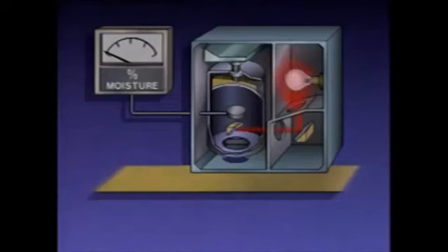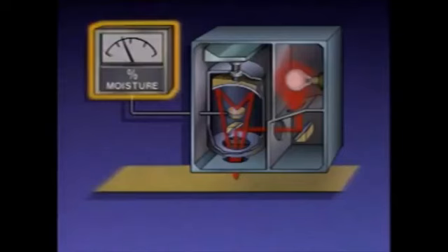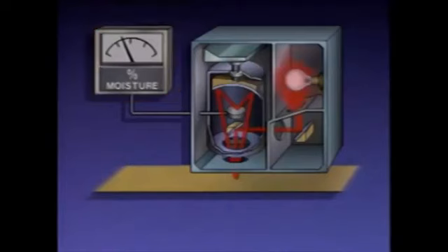During operation, the infrared waves are directed through a series of mirrors to the surface of the material being tested. Moisture in the material absorbs some of the infrared waves, but some of them are reflected up to a concave mirror. The mirror then directs the waves to a light-sensing photocell where they're measured. An indicator that's connected to the photocell displays the measurement as an indication of the moisture content of the solid material. The more moisture in the material, the fewer reflected waves, and the higher the moisture reading on the indicator.